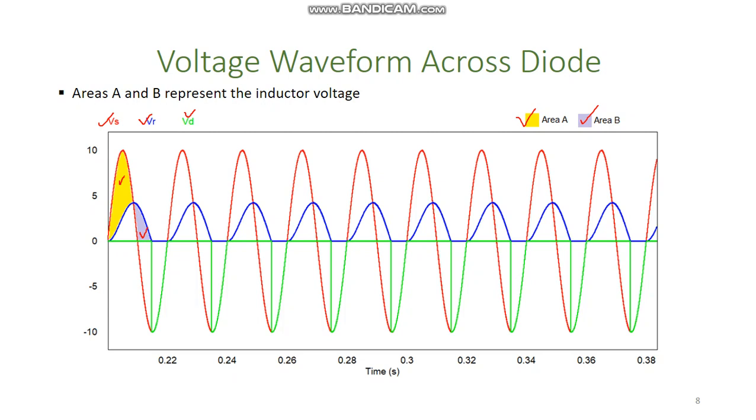So you see that the conduction angle of this diode has increased up to this point, until the inductance completely releases its energy. Only then does this diode D go into the reverse operating condition, and now the voltage will appear across this diode D.